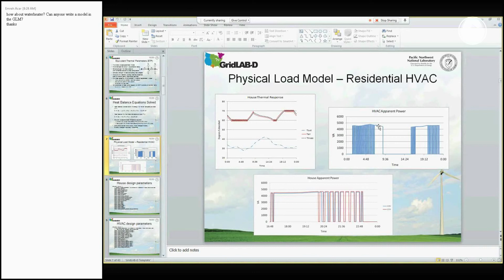So basically on a heat pump, if it's really cold out, you can't extract as much energy out of the outside air. So you see some of these temperature variations and how much power is actually drawn from the unit. Then down here you can see that the red line is with the heater running at 100 when the voltage is set to 125 volts, and the blue is representing when it's set to 118 volts.